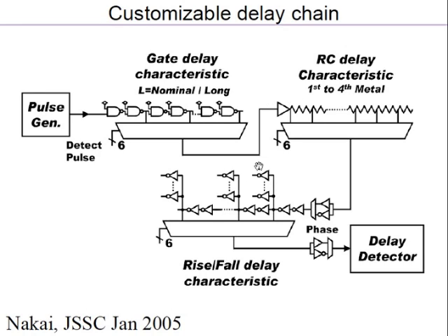See, this is just an additional piece of circuitry which is put in the chip to mimic the actual critical path. Okay, so this by itself has no significance from the point of view of actual work being done by the chip. It's just out there to help measure the actual critical path. So the idea of this piece of circuitry is that you set up the right number of stages for the wiring and gates and so on, so that you mimic the actual critical path. The actual critical path will have a certain mix of gates, certain amount of wiring. Of course, you cannot put all the gates here, because in the actual critical path you might be using all kinds of logic gates.